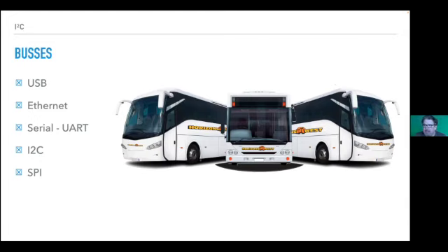I2C is different because that only uses 2 pins. The one is the rhythm, clock, clock, clock, clock, like the metronome. And then on another pin, it can talk both ways. So it can't talk at the same time, you either listen or you speak. And in I2C, you have something called a master. I'm getting into that. And then you're simply telling the device, now it's your turn to talk.